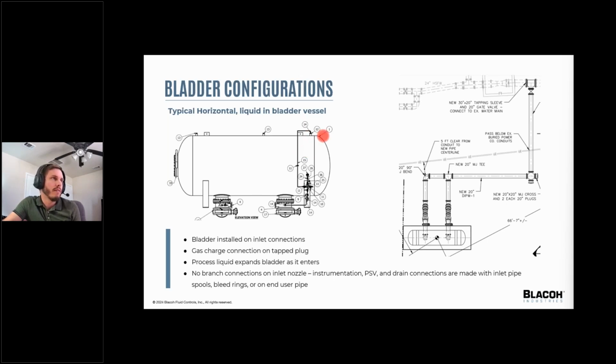You don't want to have a vessel that comes far from one of your inlet outlets and creates a dead leg where you don't really have any circulation. An exception can be taken for horizontal vessels if you have a hydropneumatic vessel with circulation and flush ports, but typically you don't have those in a bladder vessel.